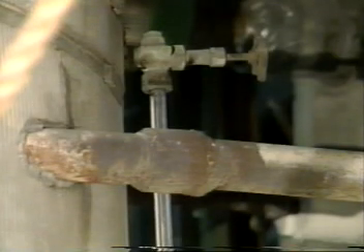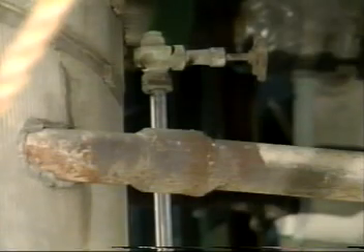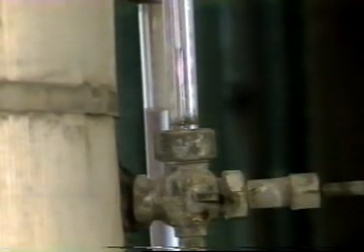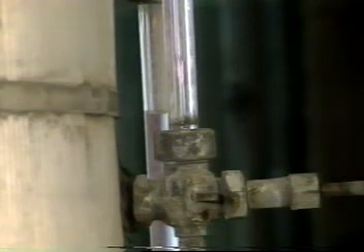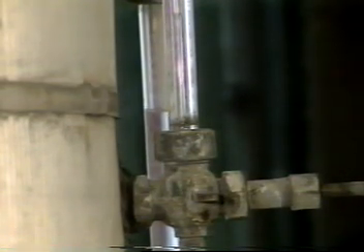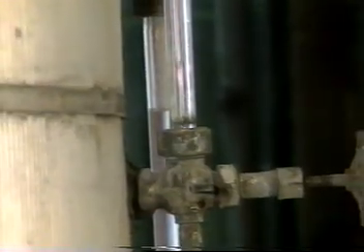So, if the tank is vented to atmosphere like this one, the top of the tube is also vented to atmosphere. In this case, two overlapping sight glasses are installed on a tank. Since liquids seek their own level, the level in the sight glass tubes will be the same as the level inside the tank and can be directly observed.